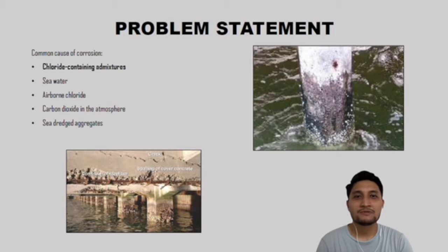Seawater is a harsh environment in which concrete infrastructure such as seawalls, jetties, and water tanks deteriorate rapidly. Corrosion of steel reinforcement or disintegration of concrete is a sign of concrete structure deterioration. Corrosion of steel reinforcement is a major cause of RC structure failure in marine environment. Water and salt ions pass through the concrete cover and make contact with the internal reinforcement. The rebar oxidizes and corrodes as the result of this process.